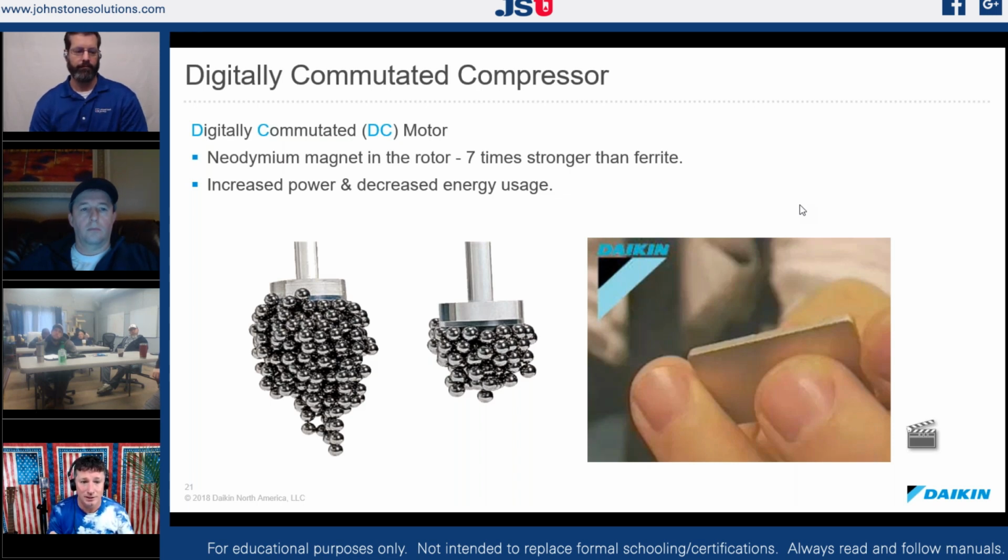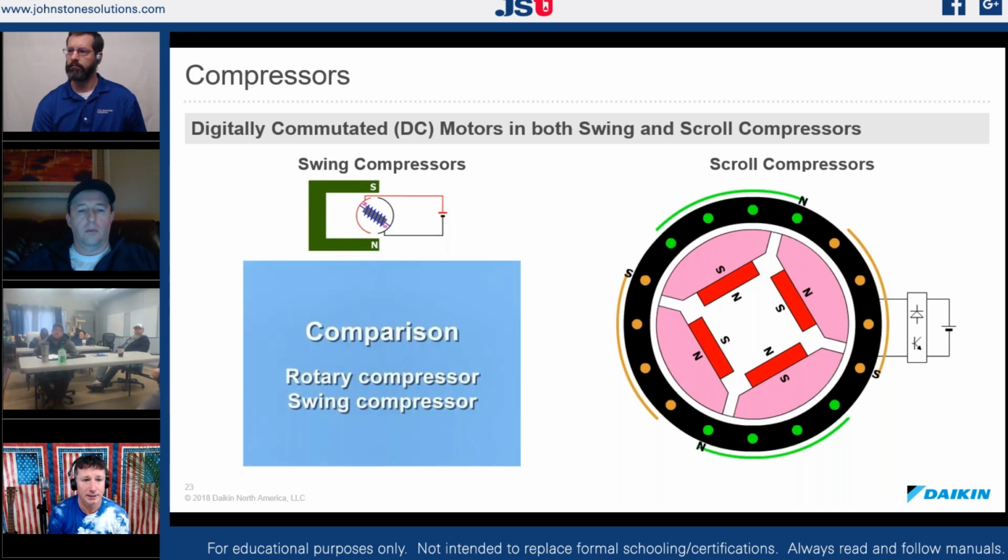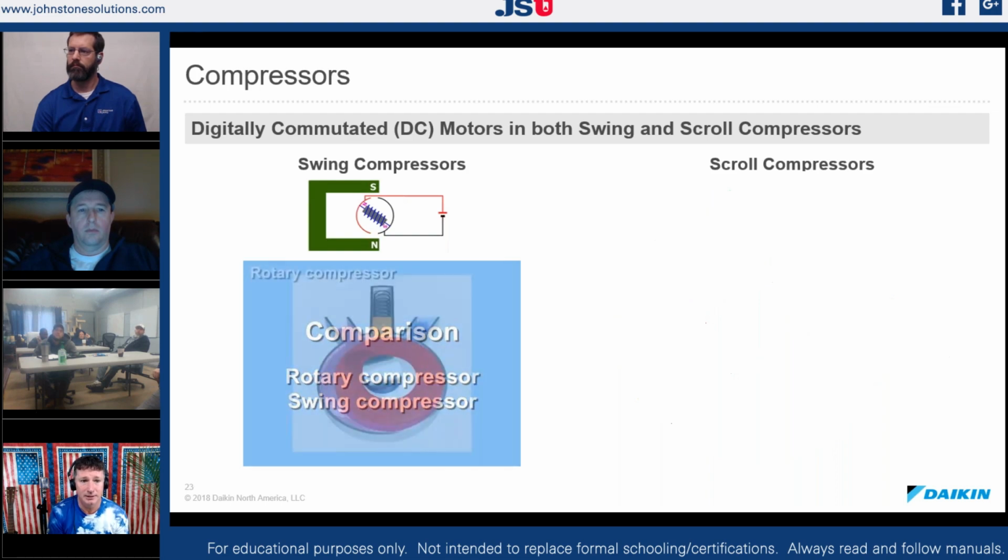So if we really want to control capacity and efficiency, can't we simply take out the permanent split capacitor motor and put in an ECM motor? That's really what we're doing. When we get into inverter compressors, all we are doing is taking either that scroll or our swing style compressor, taking out the permanent split capacitor motor, and putting in a commutated motor, a digitally commutated DC drive.